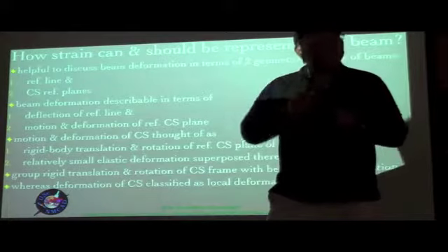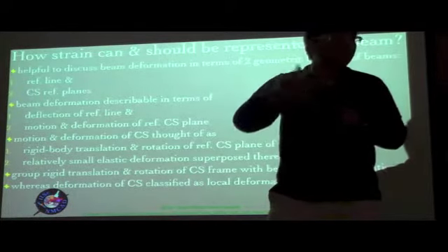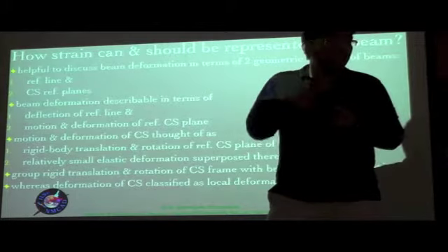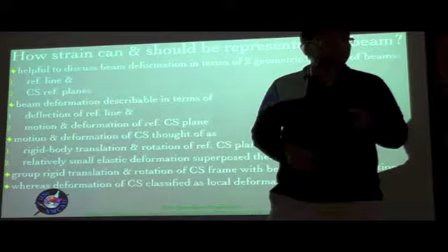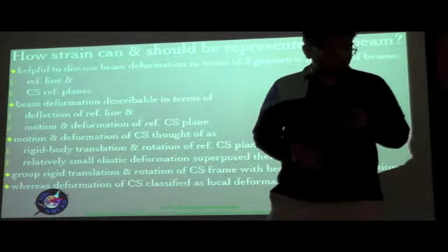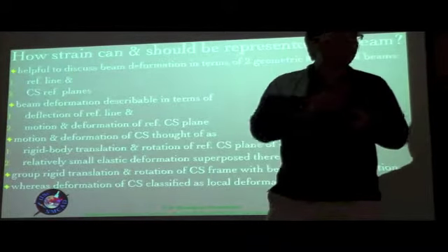Apart from that, of course, it can have additional deformations which make it warp within itself. So in this case, that line can warp in the x1 direction and have two additional rotations as well. Exactly. So W1,2 and W1,3.